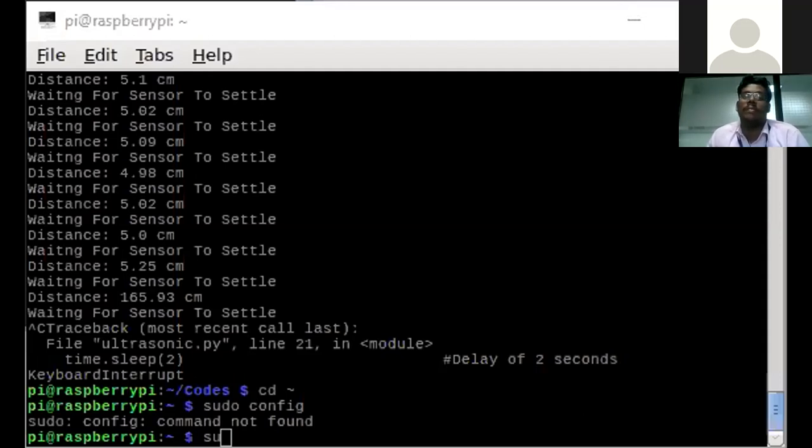So the wpa_supplicant.conf.txt file is a text file. First, you need to create a text file and mention the network settings you have provided. Based on the priority, the network setting is taken. Once the SSID has been connected, you remove the TXT extension and save it as wpa_supplicant.conf only. So whenever the Raspberry Pi boots, it looks for SSH and also wpa_supplicant.conf.